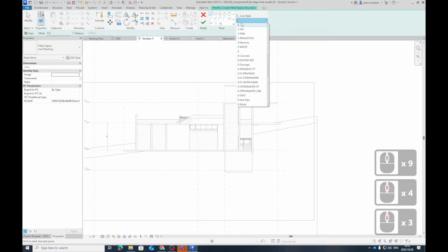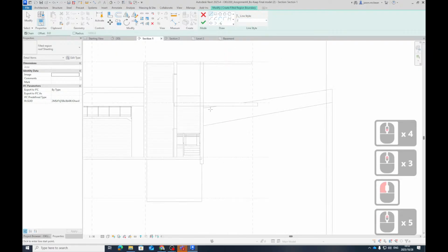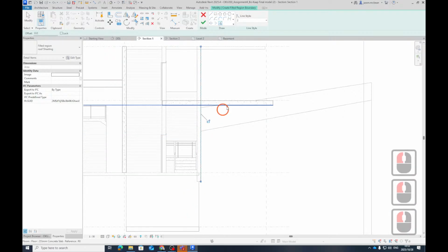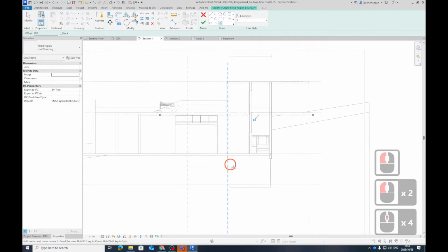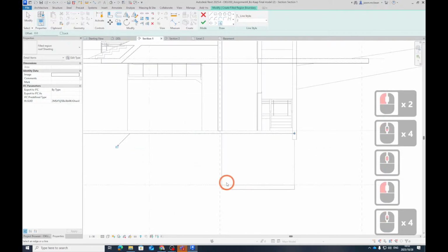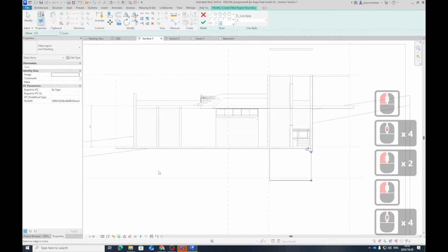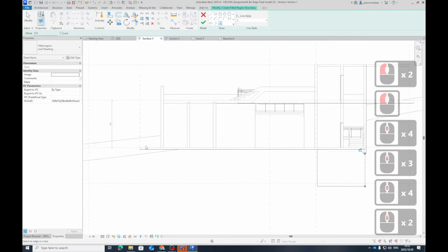Just make it line weight 6 or 5, doesn't matter. Now all that we do is very, very easy. You're going to draft, but you can use the pick line tool. So watch, I want that face, maybe there's my basement, so my natural ground line, so now we might have to go around there. Now while we're drafting, you see it might come out of the ground here.